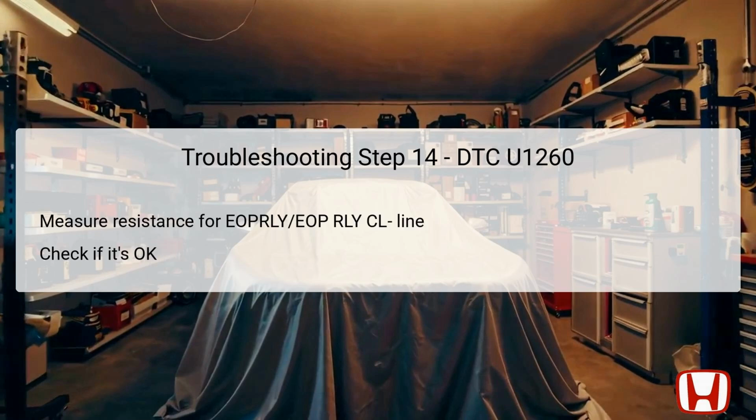The 14th step revolves around measuring the resistance of the EOPRLY, electronic oil pump relay line. This is crucial for determining whether there is an open circuit between the auxiliary pump relay and the TCM. Following the prescribed process, the technician must ensure that the vehicle is in the off mode and the relevant connectors are disconnected. A reading of 1.0 ohm or less confirms that the EOPRLY is intact.